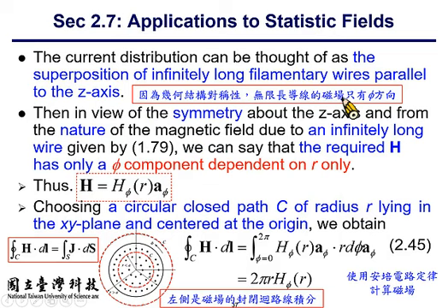So because of the symmetric property, we know that the magnetic field intensity produced by this current, which is aligned with the z direction, only produces magnetic field in the phi direction. So H has only the phi component. So you can write the magnetic field intensity H as H phi, which is a function of R, according to the value of R, it can be larger or smaller, and H phi is in the phi direction, as you can imagine.